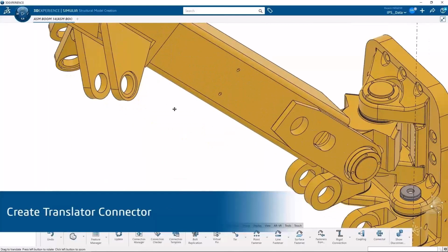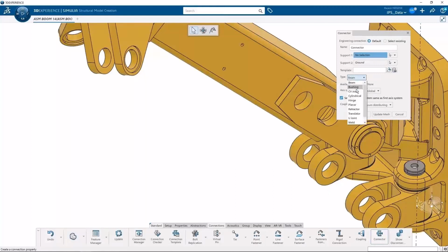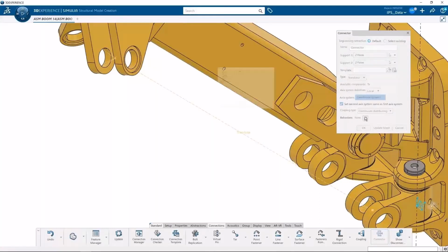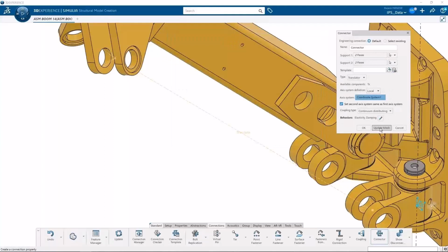Now on our project here, just like bolts, there's actually some linear actuators that raise this thing up and down. And I didn't want to simulate those and mesh those and solve those. There's actually a really cool link connector in SOLIDWORKS Simulation 2022, and I'm mimicking the same type of deal here. So it's another great way to simplify the geometry for simulation without compromising on the real world physics. You can even include the damping information here for more realistic behavior. And this process, in my case, I actually did twice, once for each side of that boom arm.